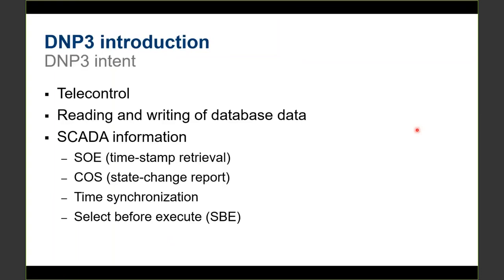But for SCADA communication between SCADA and RTU, the SCADA will be the master and the RTU will be the slave station. So in other words, some devices such as RTUs can be both master or slave depending on the implementation and settings. Relays are the slave stations only.